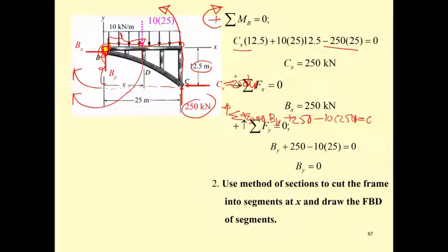Remember, at the minimum point of the cable there is only horizontal force, and this is at the highest point of the arch, there is no vertical force. We have only the B sub x, okay, and B sub x is going to be horizontal force, and you may notice that B sub x is equal to C sub x, since there is no lateral force acting on it.